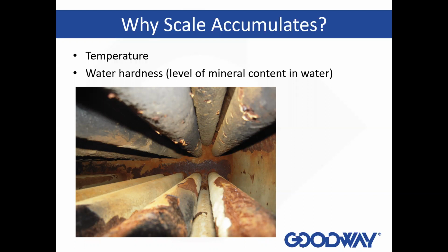So the boiler is kind of being punished over time, and there are pre-treatment devices that you can use, like a water softener, so that's going to strip out the minerals that would otherwise end up baking out on the inside. But a lot of times you don't have a water softener bank.